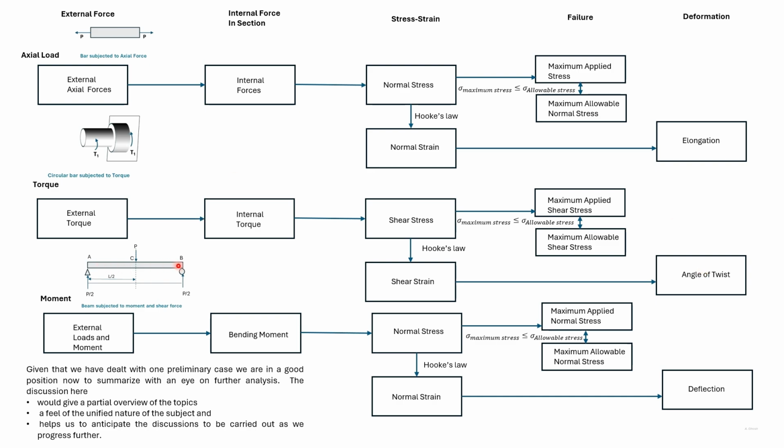In this case, this beam has been subjected to a load only, but beams can be subjected to loads and moments. If we take a section between A and C, then it will be subjected to both bending moment and shear force. However, here we look at bending moment only. Determining normal stress from the internal bending moment is again more involved than this straightforward case and is given by a formula.